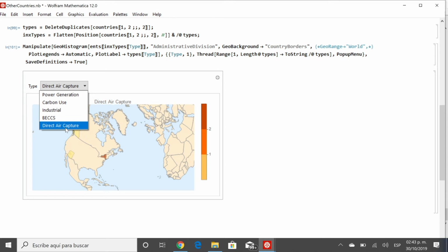One of the issues also is that you need to store this CO2 in the ground so it doesn't filter out to the atmosphere again. Otherwise, you're just shifting the problem away. If it leaks out in 200 years, then you're going to have an issue in 200 years' time. That's why the geological location is also critical. It's not just put it wherever there is a source of CO2. You have to consider the ground on which this facility is located, and make sure it's appropriate for storing the captured CO2, and that it remains there for the longest time possible. Because leakage, even if it's 1% per year, is going to be an issue.